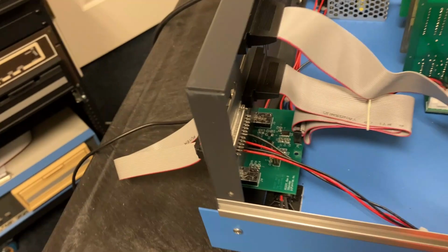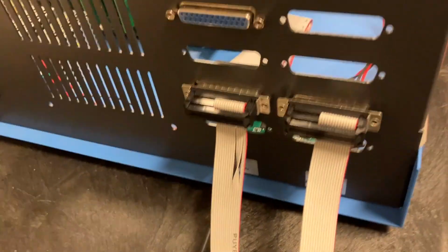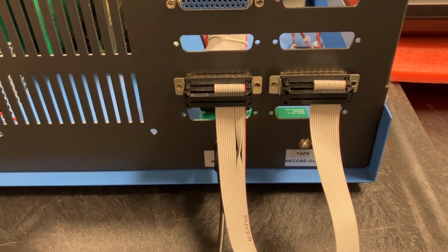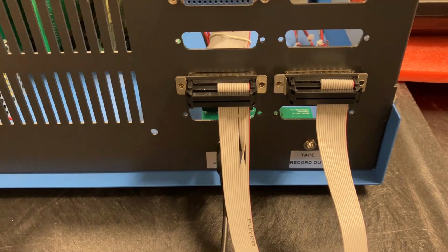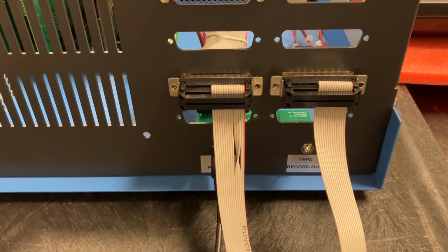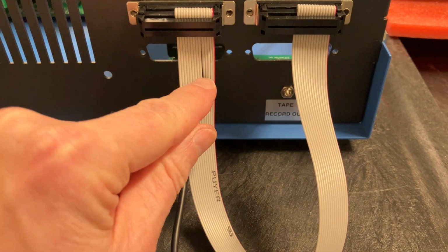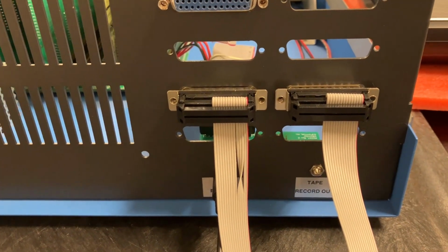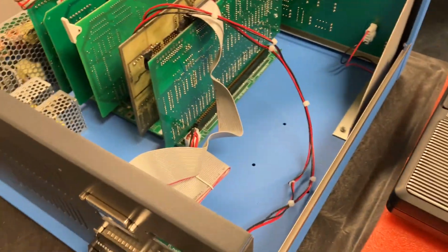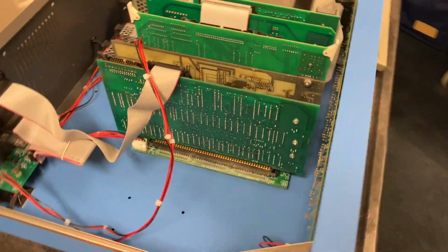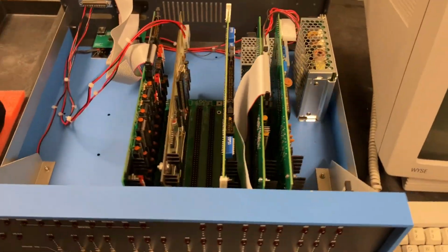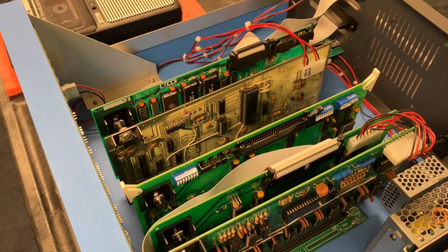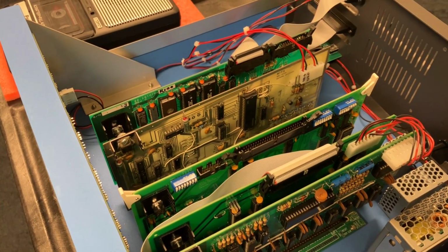And then to hook the modem to the serial board, I just have a jumper cable going between those two DB25 connectors. Now our modem is connected to the serial interface board. Now both of those connectors are wired as DCE, so I have to swap pins 2 and 3 between them, and that's what this little twist does right here. But for several reasons, I want to leave those both as DCE, just like I mentioned in that previous video. All right, so that's all it would take to get an 88 SIO version A, which is RS-232 already, up and running inside your Altair as a completely equivalent drop-in replacement for the Altair Cassette Interface.